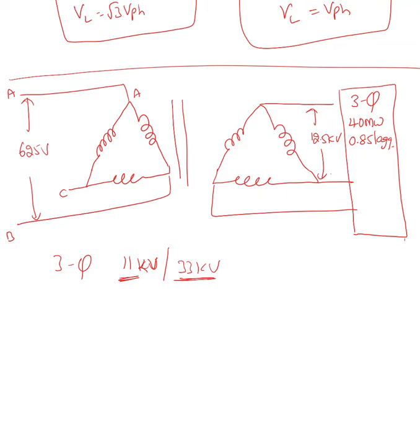Unless I specify, anywhere in the world, we always take that as a line voltage. Now in this example, he gave us the line to line voltage on the primary side is 625 volt. You can see these two lines indicate it's an ideal transformer, and the secondary is connected to a three-phase 40 megawatt 0.85 lagging power factor with 12.5 kV load. The question he's asking about, find the turns ratio.